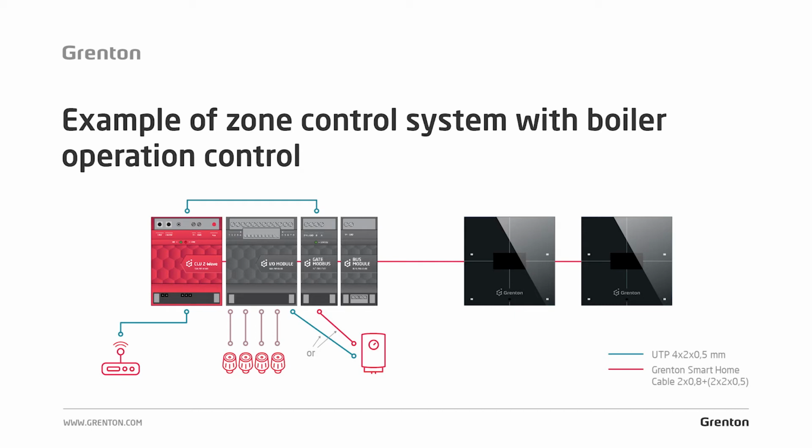You can connect it via the so-called thermostat input. Most boilers I know have this input. Through one of the relay outputs, you can now say to the boiler, turn off, or turn on. Or, if the boiler used in your installation has a communication interface which allows more complex integration, then you can connect such a boiler through a suitable gateway. For example, it can be a Gate Modbus or Gate HTTP.